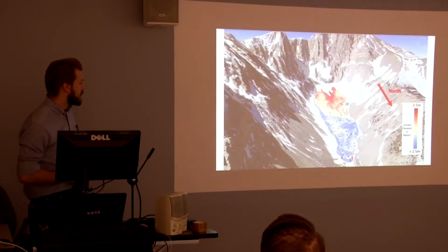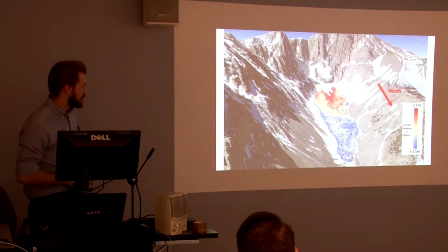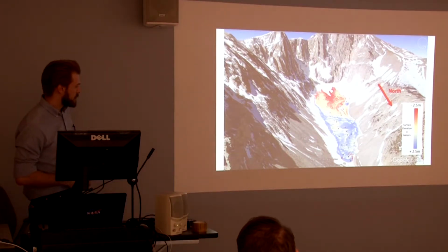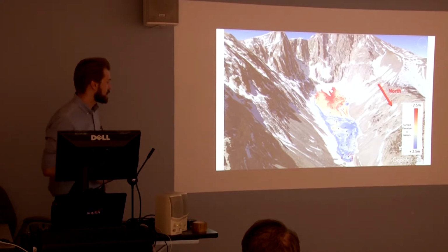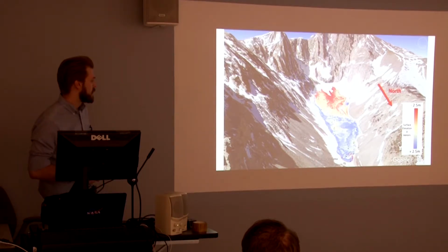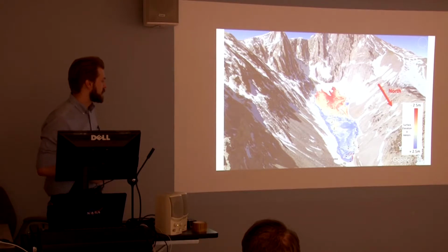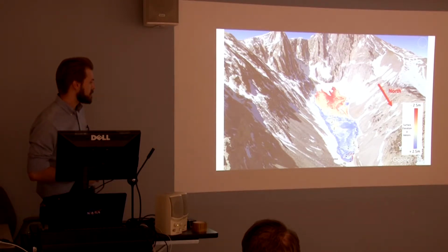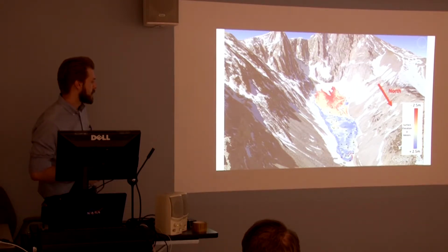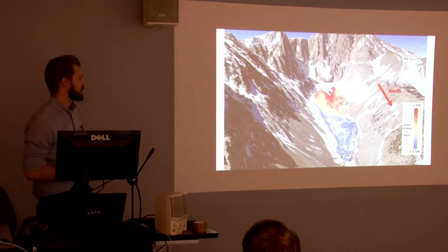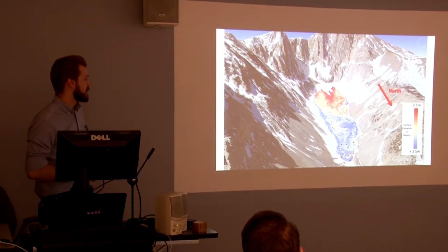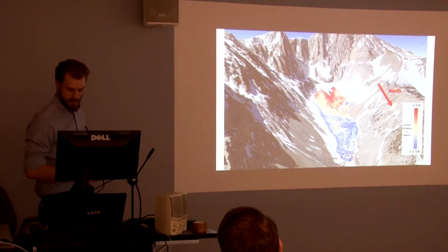So looking at that a bit closer, these are the ground control points that were used in 2016 across the glacier, and these are the ones that were used in 2018. And collectively, those are all the ground control points that we used to create this map. Each of those were recorded for 5 minutes at the ground control point.